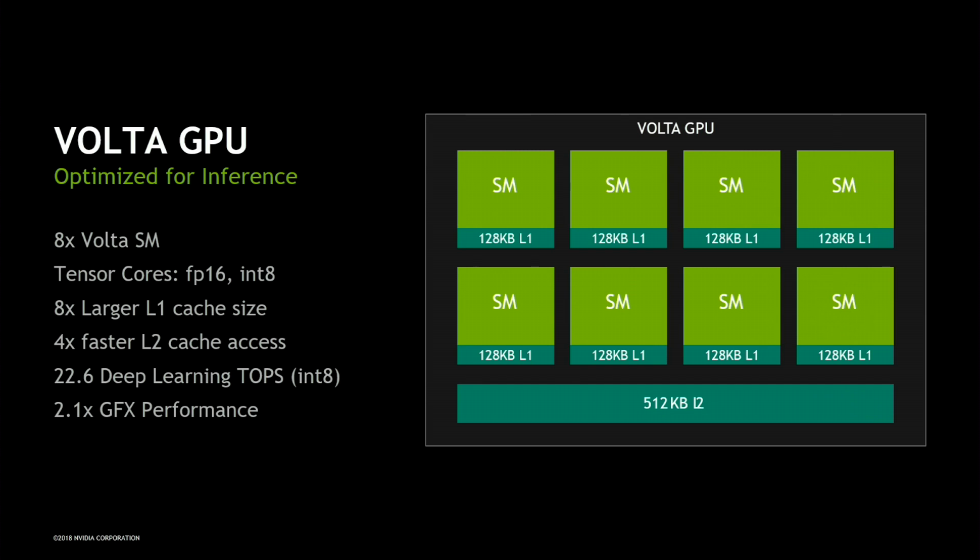Let's talk about the GPU. So we looked at the Volta GPU, and the Volta GPU was designed to improve compute and deep learning performance. Now, unlike Volta, which is oftentimes used in a training environment and servers, right? Our GV100 is a big GPU. We looked at what we need to do to optimize this for inference. So one of the things we did is we took the Tensor core, which is the core in our GPU for deep learning acceleration, and we added int8 support. And the int8 support runs at 2x the rate of the FP16. So we can do int8 even faster. And that is commonly used, as we've even heard today, in the deep learning inference space.